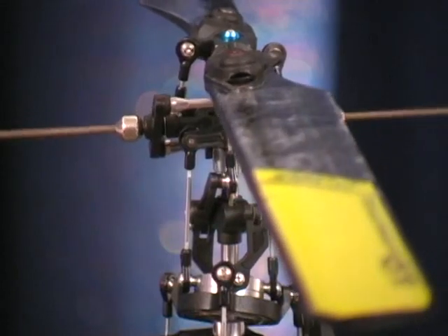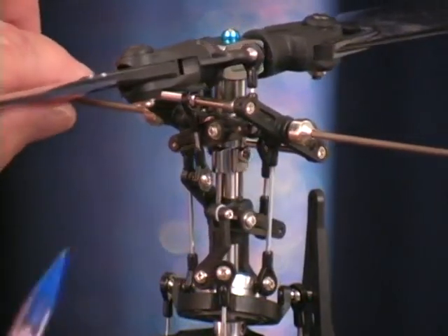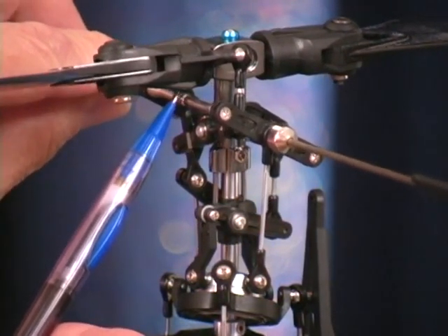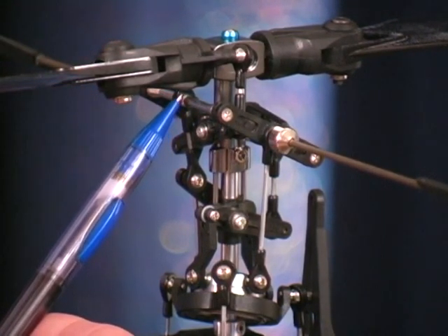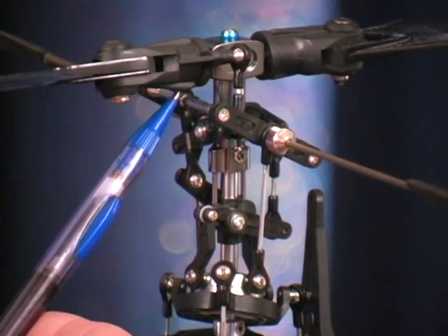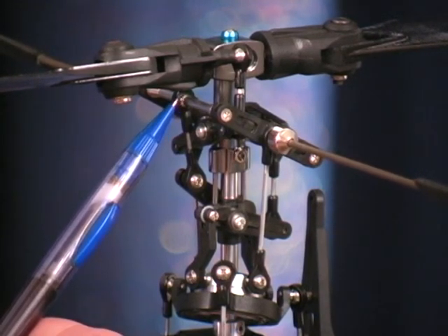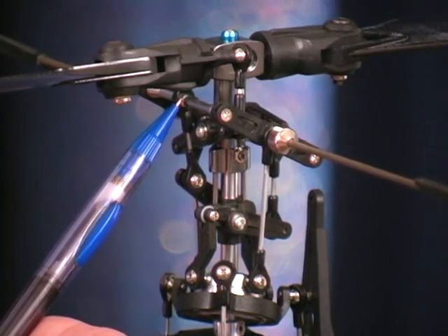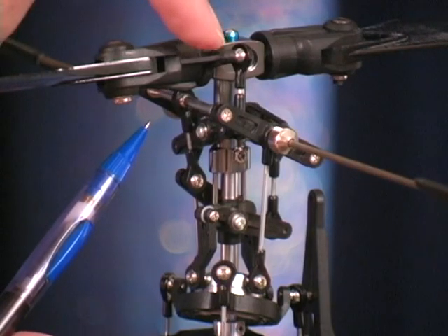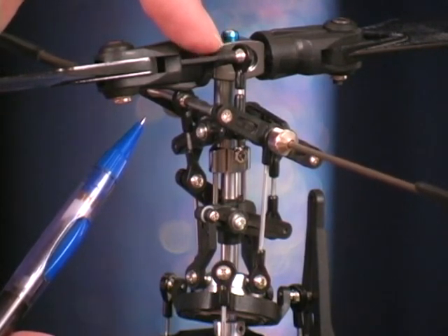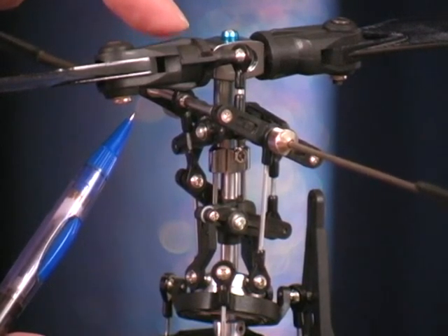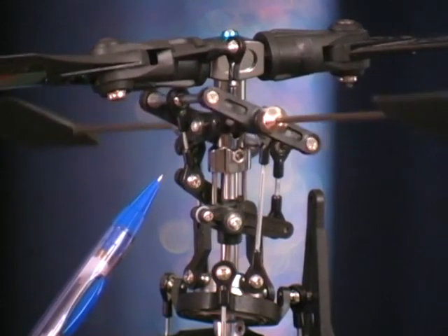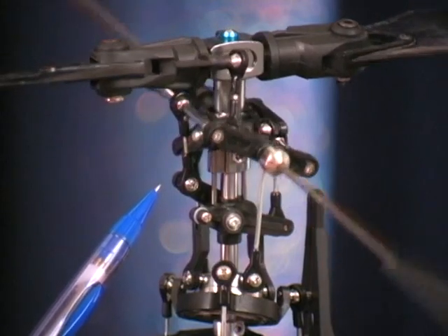Okay, here I'm picking up a little binding, and that's with this ball link right on the bottom reinforcement of the blade grip. I showed you how to trim this reinforcement down a little bit to eliminate the binding. I haven't done it in this helicopter because after the DVD I'm going to flip the pitch arm from the trailing edge to the leading edge, so I'll end up sanding what is now the top of the blade grip. Okay, and that looks pretty good.